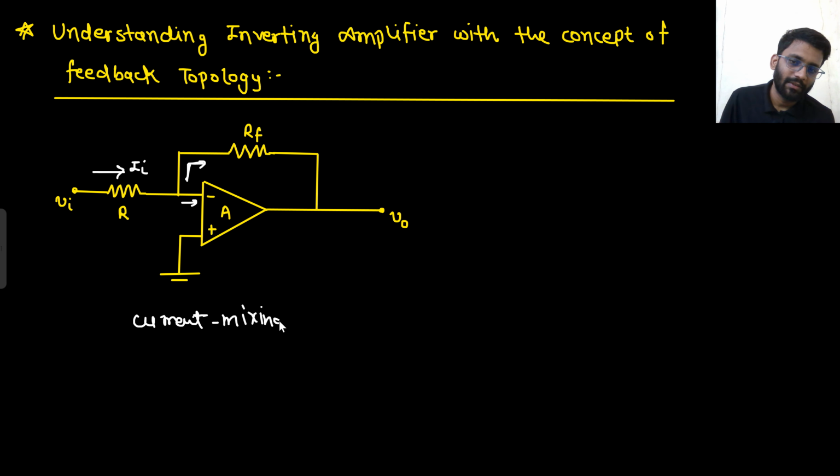What about sampling? So what is the method of sampling? The simple method of sampling is that you just put V naught equals to 0. If you put V naught equals to 0, is there anything coming in the feedback path? No, there is nothing coming in the feedback path. If I put V naught equals to 0, there is nothing that would come into the feedback path, right?